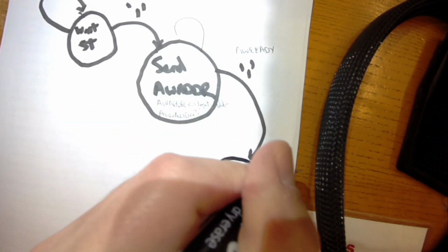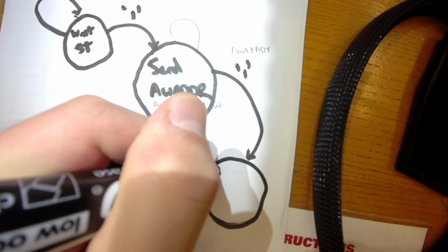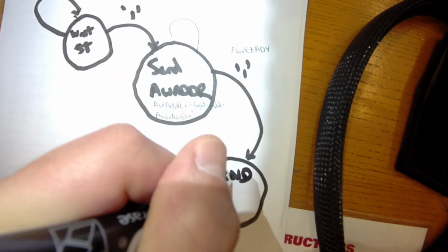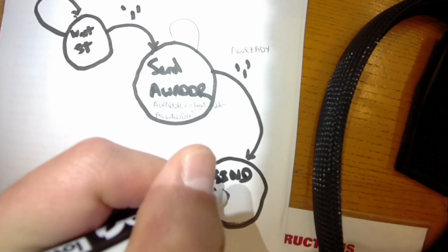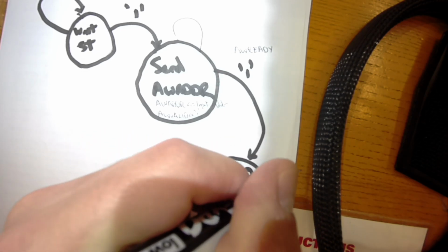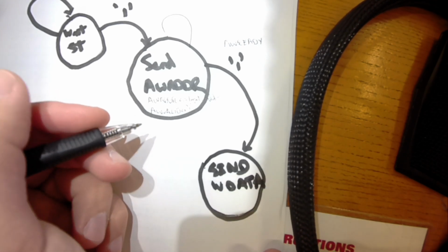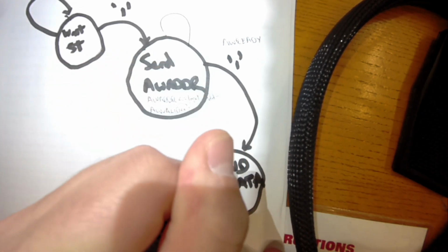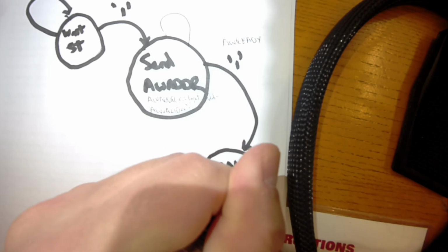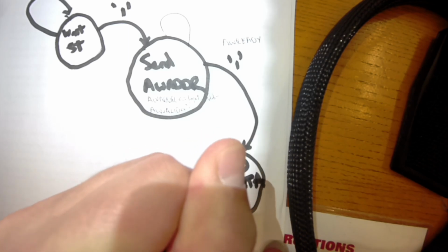If we want to really use our AXI terminology, I would probably just call it send write data. Ugh, you're never sending read data from an AXI sender or initiator, but send W data is happening in that next stage. What do we need to do for send data? Yep, and that would be W valid. We're sending W data.